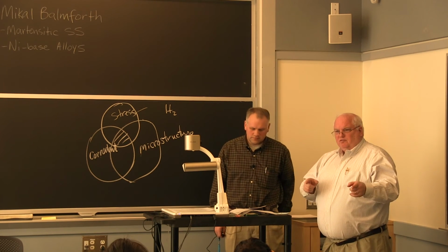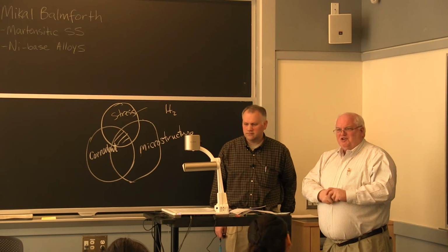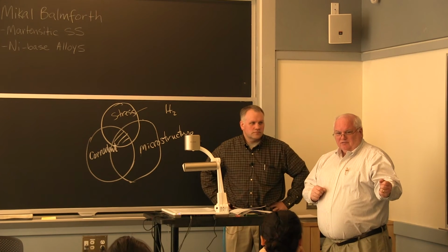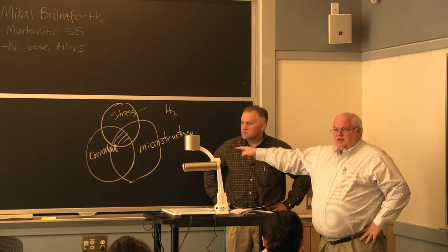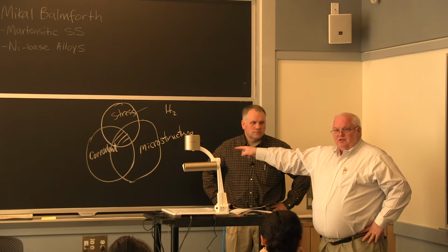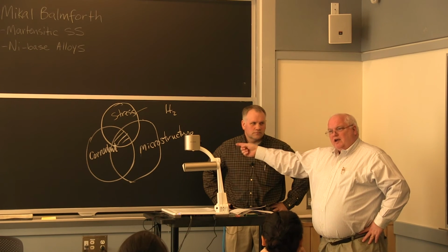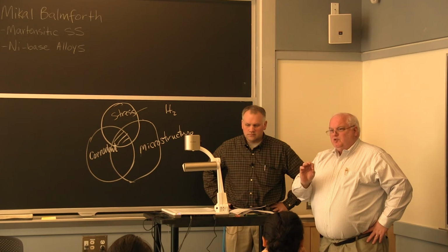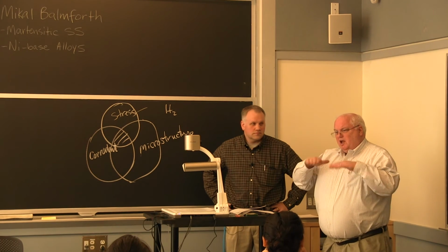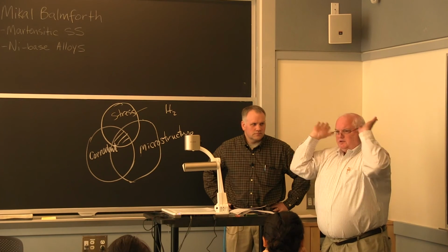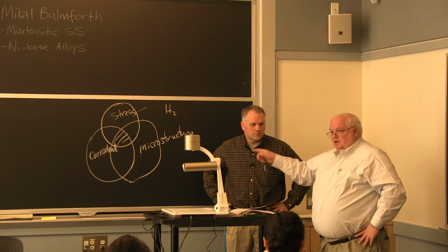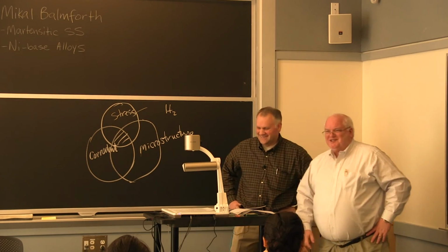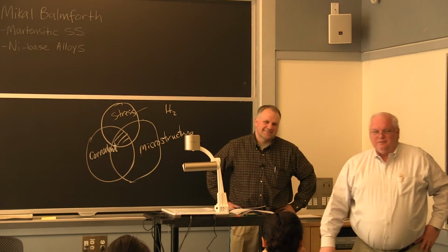One occurs at the anode and one occurs at the cathode. Why? Because the corrodant is hydrogen, which is positively charged. In chloride cracking, it's chlorine, which is negatively charged. So you can distinguish them at one level, but most of the time they just throw it all together. So yes, I did cover stress corrosion cracking yesterday, but only a subset of hydrogen.